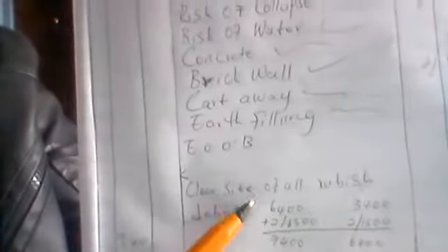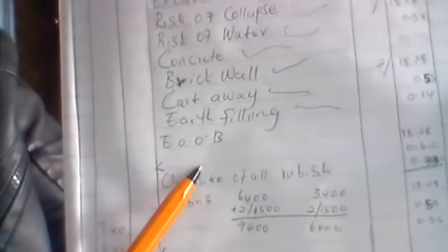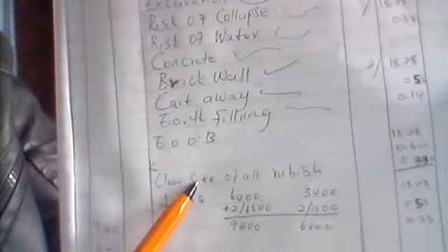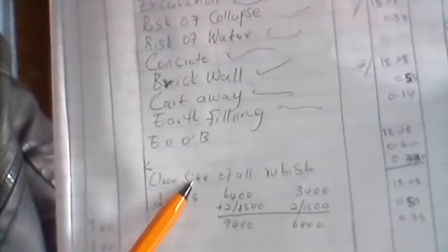The last part is extra over brick. Extra over means outside. We need to measure the length of the exposed bricks outside. When you write your statement, it's extra over brick facings, including the wall ties.